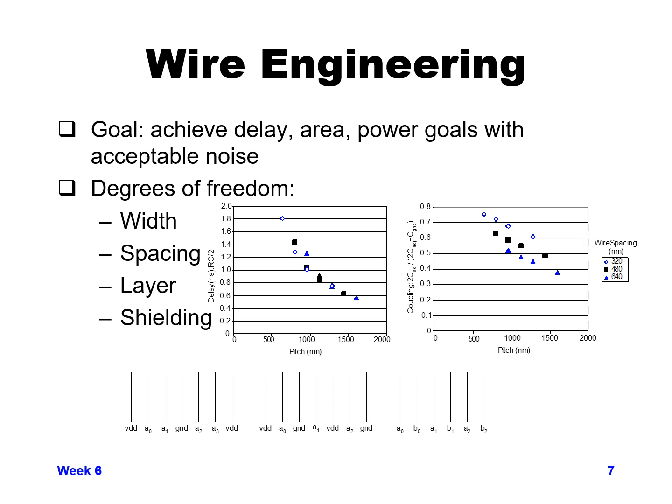The problem with this is you get many fewer signal tracks because you're taking every other track for a power or ground track. But it does give you the most noise insensitive design. So it's very good for noise, but it does drastically reduce the total number of tracks that you have available for routing real signals.